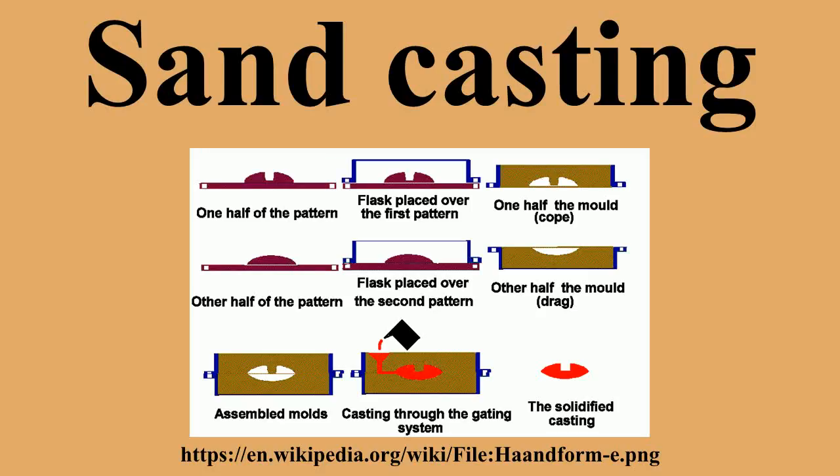In the case of metals that are significantly heavier than the casting sand, such as iron or lead, the casting flask is often covered with a heavy plate to prevent a problem known as floating the mold. Floating the mold occurs when the pressure of the metal pushes the sand above the mold cavity out of shape, causing the casting to fail.